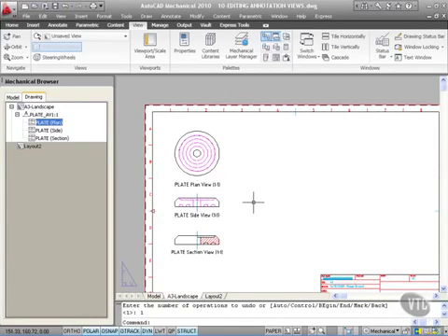You might click undo a few times and think, oh, it hasn't changed. I'll leave it, delete it, go back to it. Don't do that. Undo as far as you can to make sure that you can see what's going on. Undo is a very useful command, but it can be used erroneously like I've just proved. Make sure you undo all the way back because there's 4 or 5 steps there when you actually change your label, when you edit your label in your annotation view. So as you can see there, annotation views, easy to edit as long as you're careful.